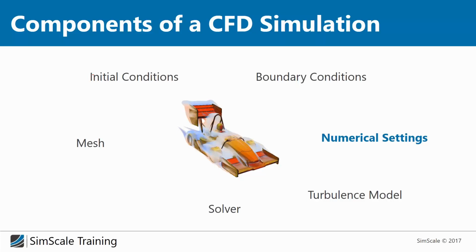And usually, as a, let's say, less experienced user, you should not care so much about numerical settings and initial conditions, for example. Basically, the standard settings and default settings, which are on the SimScale platform, should be fine for most of the simulations. And there is one other thing I would like to talk with you about, the so-called turbulence modeling, which is very important for wind comfort prediction, especially for wind load prediction. And Per will talk about it also during his presentation.